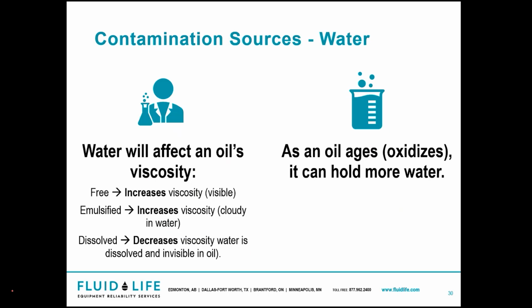So water, it also has a huge effect on it. Free water, where you see the water and oil separated, that is called free. It increases your viscosity. Emulsified, where you have that mixed creamy, milky color, is also going to increase your viscosity. And dissolved, you're not going to see the water in the oil. It just very slightly decreases your viscosity, as opposed to emulsified and free, which can significantly change it. And as your oil ages and your additives get consumed, the more likely it is to hold on to water.